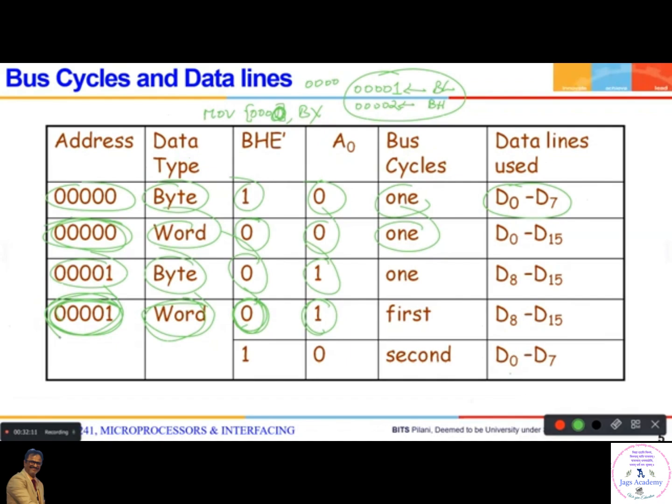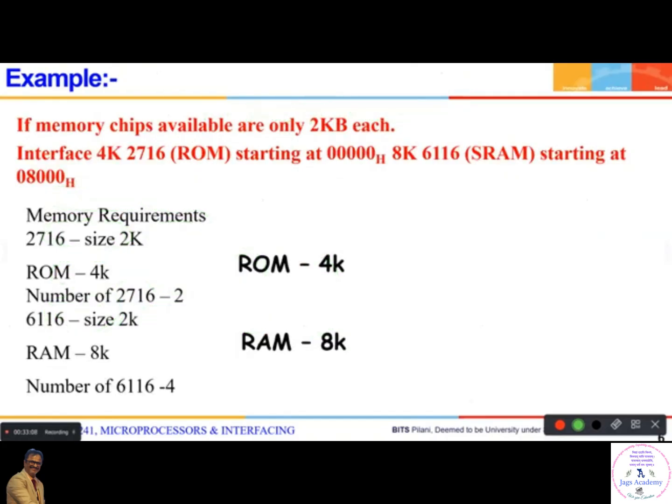That's why, have you seen whenever you debug in the lab, the addresses are generated by the compiler itself. All the memory addresses, when you have executed the program in the lab, are automatically allotted. Even though you used ORG, it didn't work, right? Have you observed it? Why? Because your compiler does memory allocation, address allocation, in such a way that whenever you want a word access, it will try to do it in one bus cycle only. It won't create a situation where you have an odd address like this and try to transfer the data. So this is about how the 8086 microprocessor transfers the data.